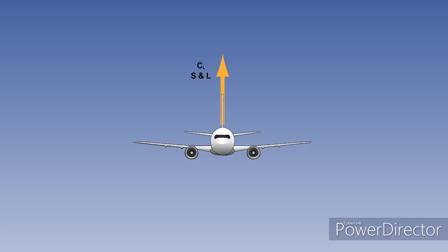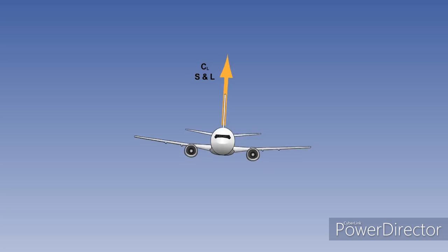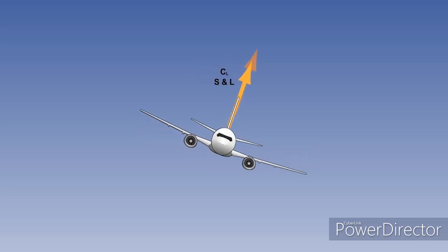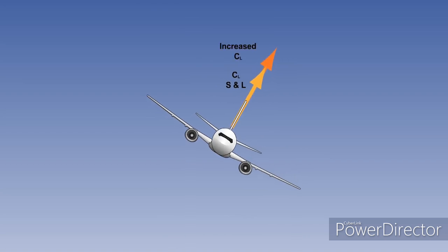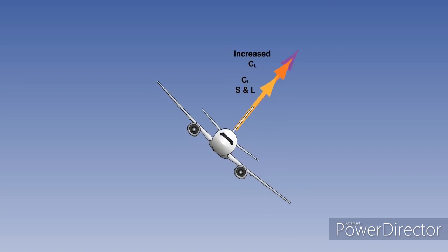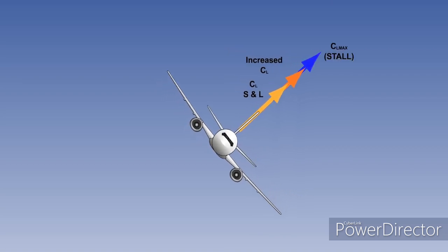In straight and level flight at CL max, it would be impossible to turn and maintain altitude, as trying to increase lift would stall the aircraft. If a turn were to be started at a speed above the stalling speed, then at a certain angle of bank, CL would reach its maximum, and the aircraft would stall at a speed higher than the 1g stalling speed.